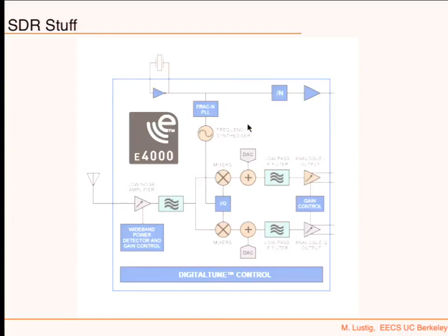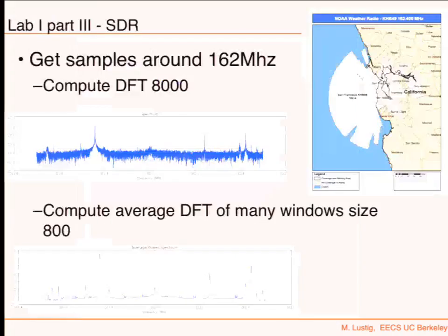Okay? If you look at what the chip does, look at this. This is the demodulator. It goes through these two mixers, and then low-pass filter, analog to digital is exactly the same thing. It actually implements this. So this is why these are complex.